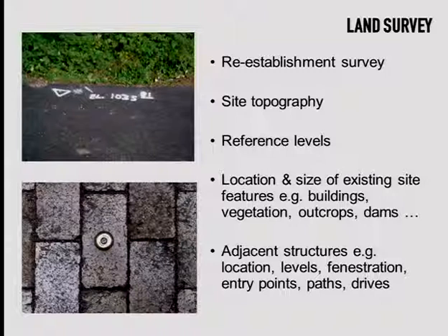And you usually find that with these sort of markers. When you see something like that, and a survey mark, they're pretty easy to spot because they're in triangles. And that particular triangle is around a nail that a land surveyor has driven into the ground, and he's given you an existing level there and a height of that level. Okay, so that's a relative level.